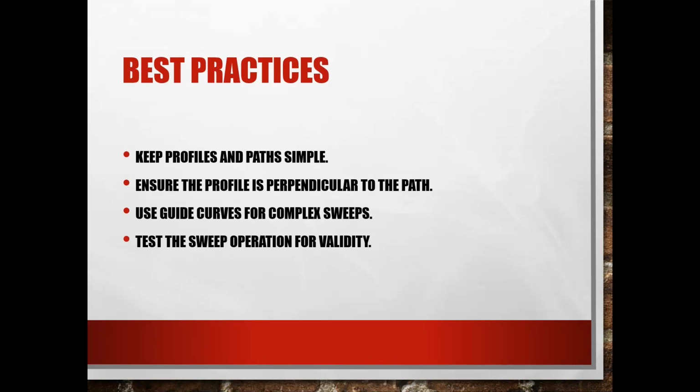All right, some of the best practices that I can tell you is keep everything as simple as you can, especially when you're drawing these things in SolidWorks and Inventor. The reason I'm talking about both of those is that when you're putting dimensions on things, your sketch can go a little wild sometimes. So if you keep it simple, locking your constraints and putting all your dimensions and angles on your drawing, that tends to lock it down. Especially when it comes to creating those three-dimensional sketches in all of these programs, keep it as simple as you possibly can. Don't try to get too overly complicated.